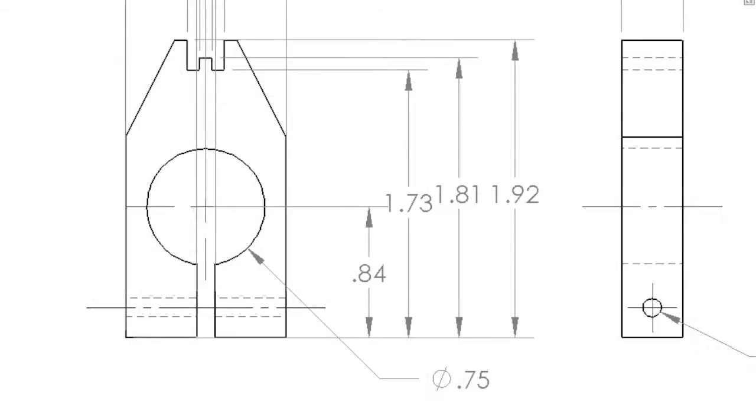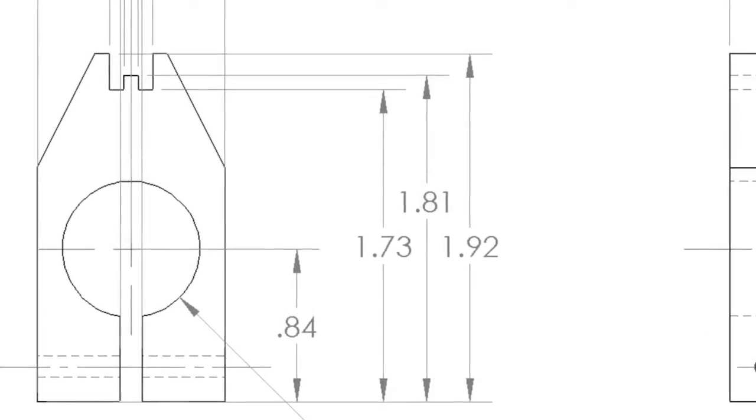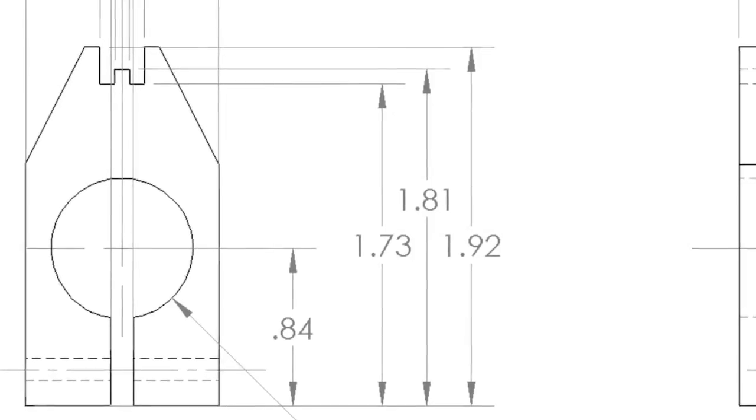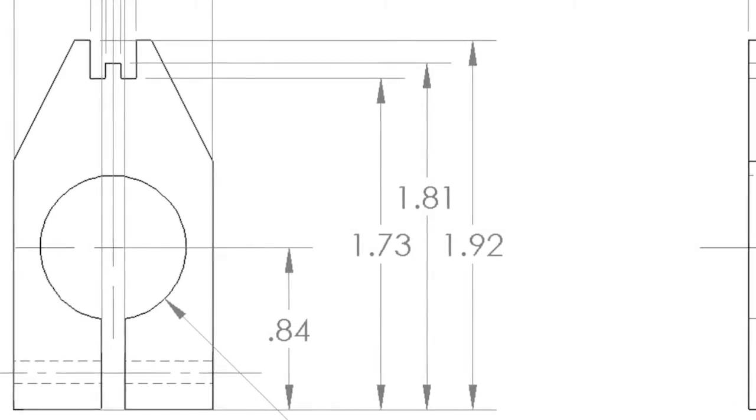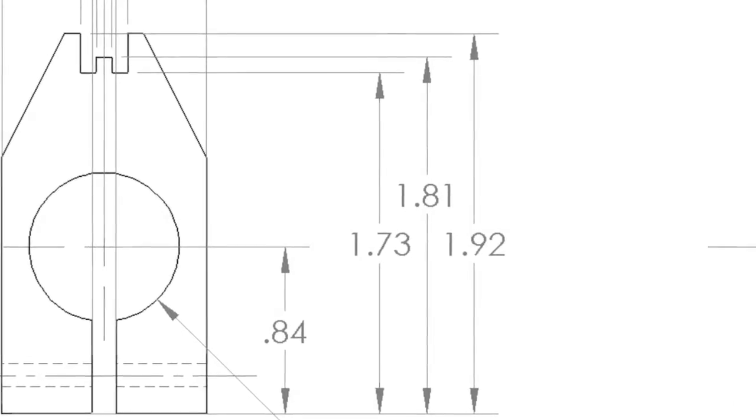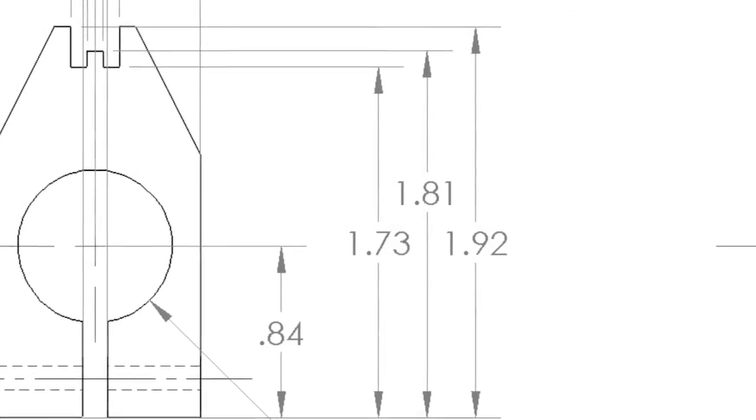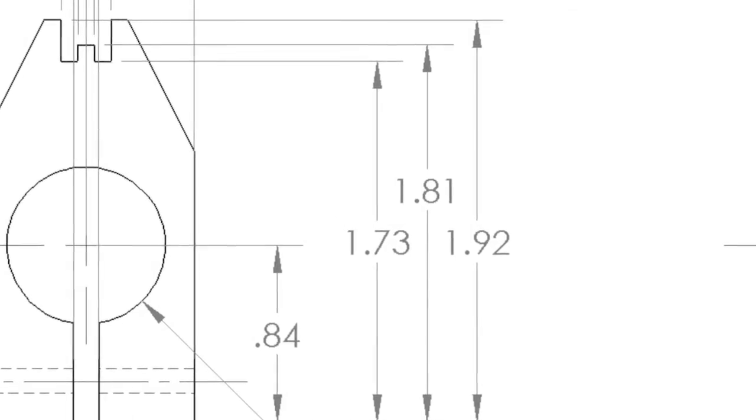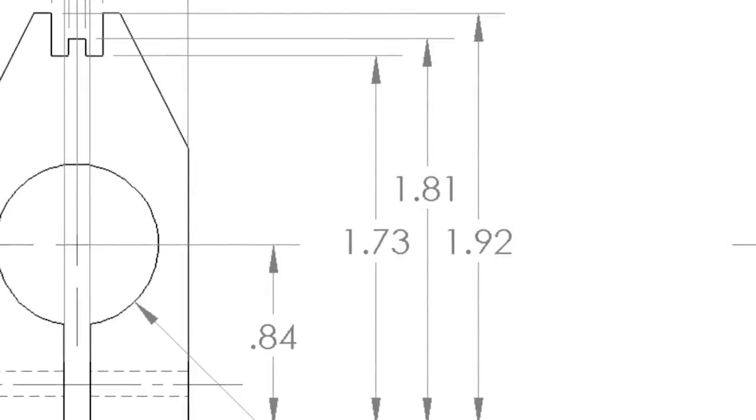It is a general requirement that the dimension values be placed in the center of the dimension line. However, when using dimensions that are staggered, it helps to offset the dimension value from the center placement in order to distinguish one value from another. Simply put, staggered placement makes a drawing much easier to read because the reader can more quickly understand what value pertains to what dimension line.